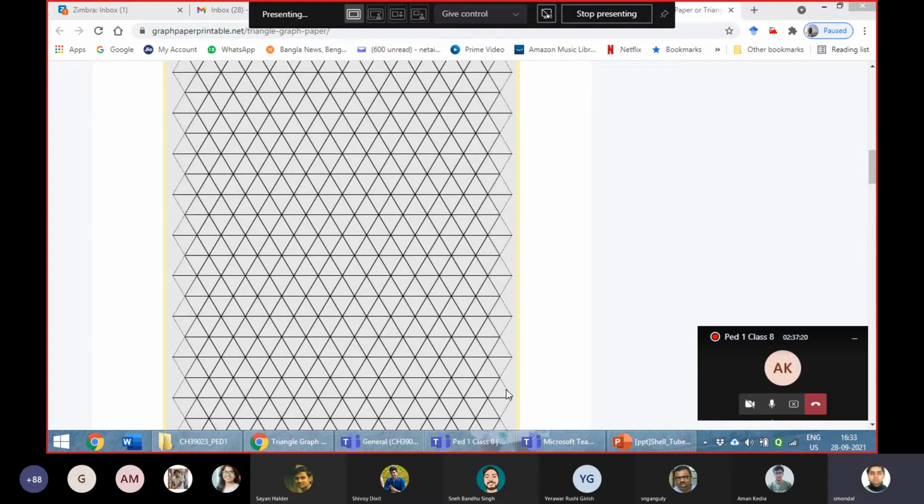And this could be used for your triangular arrangement. So you have to draw your circle essentially over this triangular graph sheet. Similarly, the normal graph sheets can also be used to draw for circular rectangular pitch arrangements or square pitch arrangements, or you can also prepare your own lines with the vertical sort of square grids. So this is how generally it is best or easier to arrange your tube holes in the tube sheets.